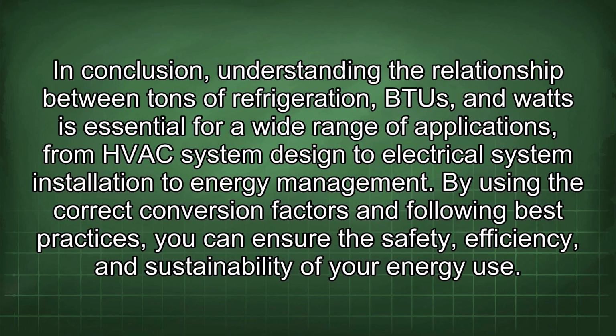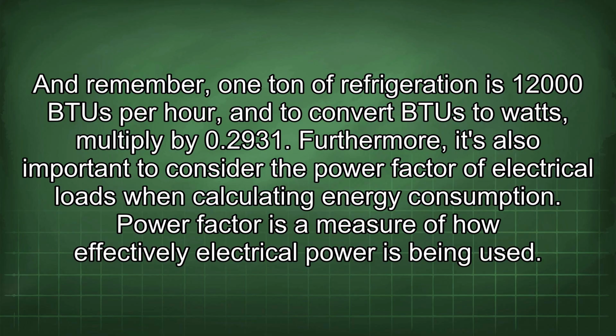In conclusion, understanding the relationship between tons of refrigeration, BTUs, and watts is essential for a wide range of applications, from HVAC system design to electrical system installation to energy management. By using the correct conversion factors and following best practices, you can ensure the safety, efficiency, and sustainability of your energy use. And remember, 1 ton of refrigeration is 12,000 BTU per hour, and to convert BTU to watts, multiply by 0.2931.